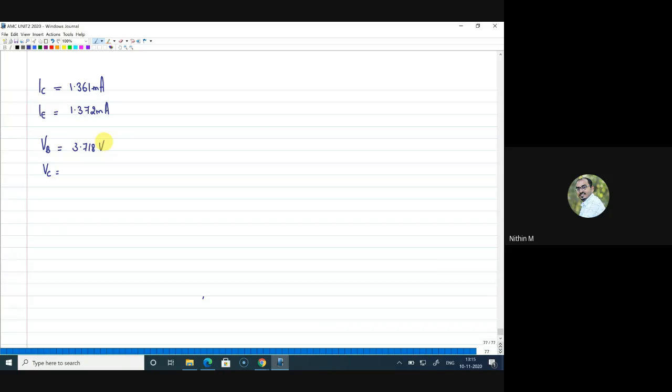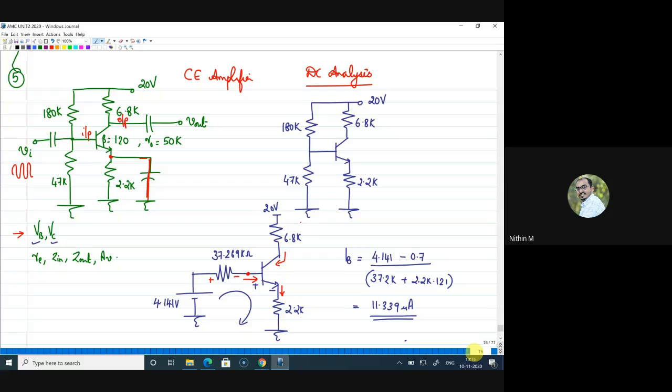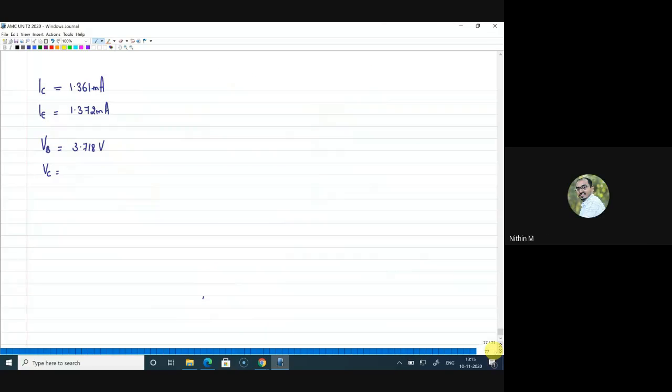Okay. Now next is VC. So how will I write VC? Let me check with Bhavana. Bhavana, are you there? Yes, sir. Tell me what is VC? VC we can get by 20 minus 6.8K into IC, right? Yes, sir. So what is the VC value? Yes, sir, I'm doing. Let me check with Pradyumna. Pradyumna? 10.745. Yes, it is 10.745. Thank you, Pradyumna.